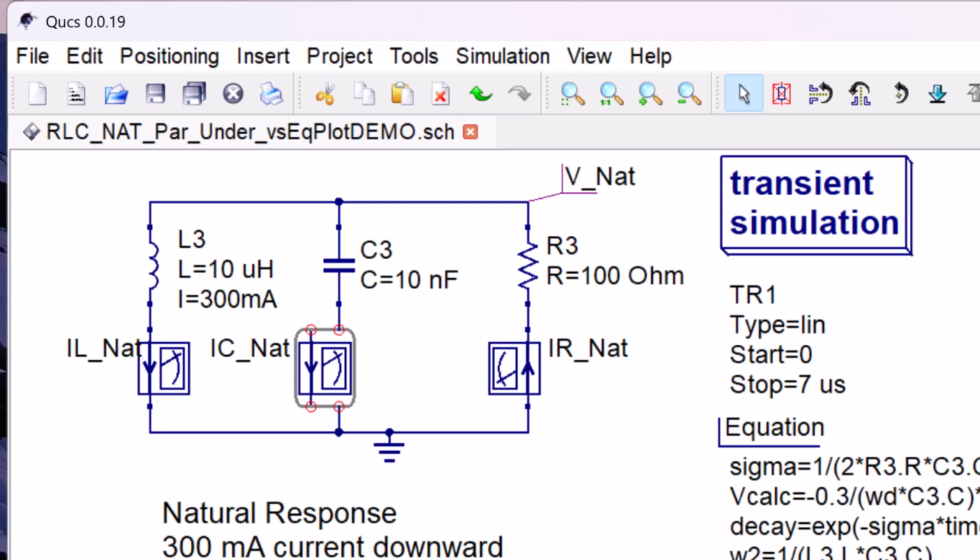Now we have the meter direction arrow oriented correctly, but the meter legs are disconnected from the rest of the schematic. Holding down the left mouse button, drag the meter to the right towards the wires. We can see from the red circles that our meter is still disconnected. The red circles on the connection points indicate no connection.